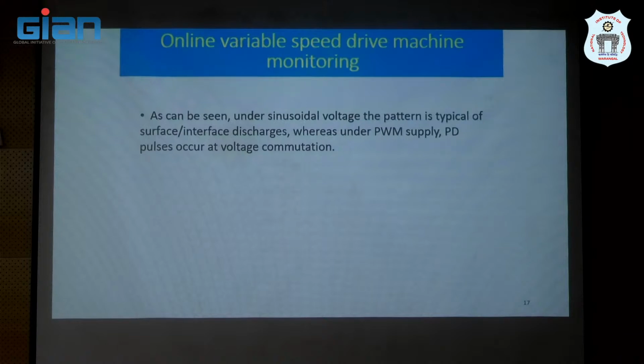Or even if there is any stress component parallel to the surface of the insulation, we will get surface discharges, like the corona discharges in a gaseous medium. Like that, these stresses will have their own natural way of getting discharges with respect to the AC stress.